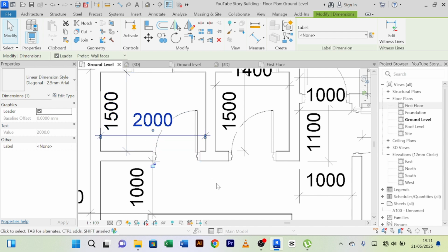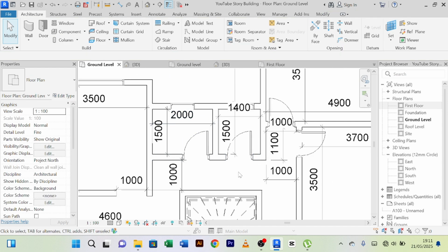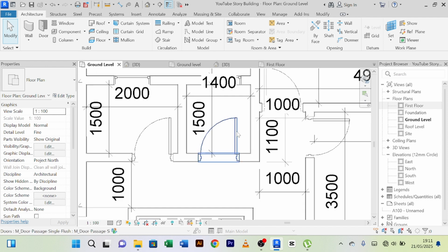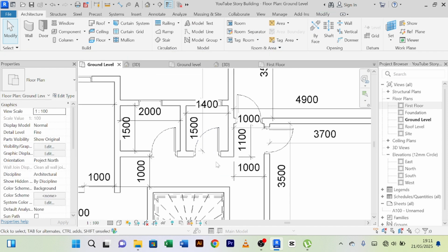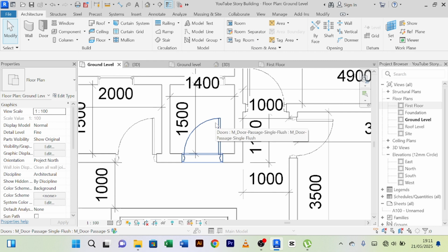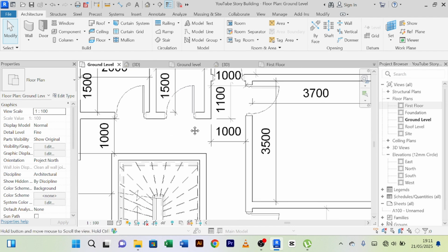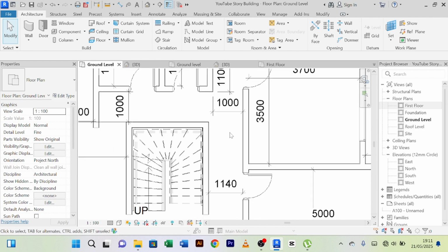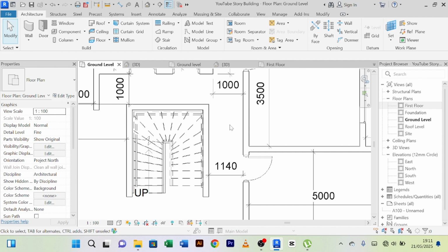And then this one, we shall also move it the other side. For the washroom, I think we need a sliding door, because you realize this door takes 900 millimeters of space. That means it will leave us with a very small room.